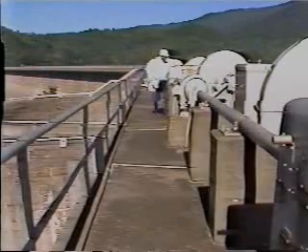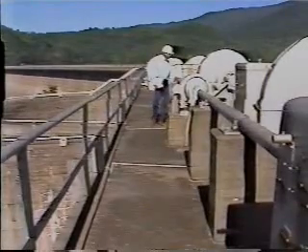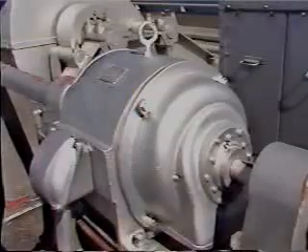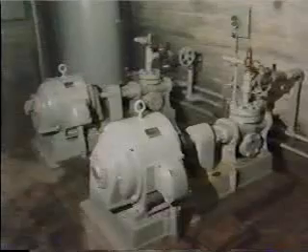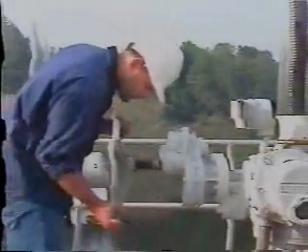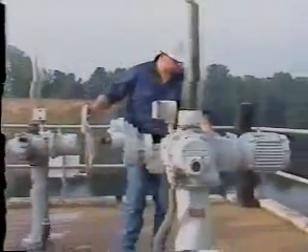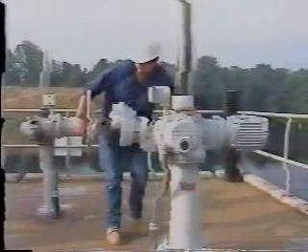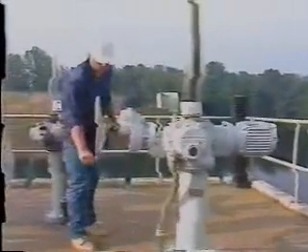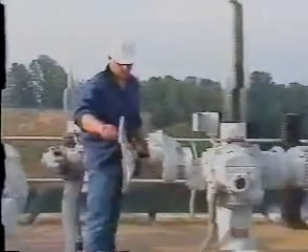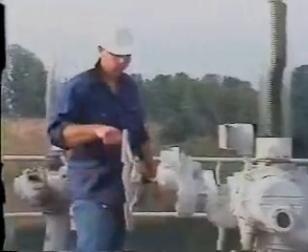As you learned in the text, mechanical devices called hoists and operators are used to open and close gates and valves. Hoists and operators can be powered manually, electrically, or by hydraulic pressure. Electrical and hydraulic operating systems should have auxiliary or emergency backups in case the primary power source fails. Auxiliary power can be provided by engine-driven generators, engine-driven oil pumps, compressed air, or manual systems.